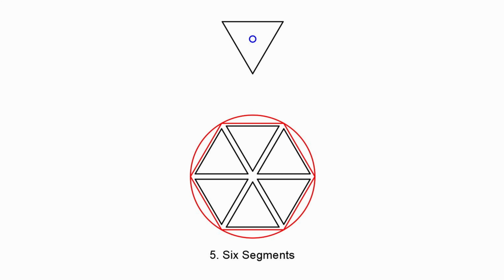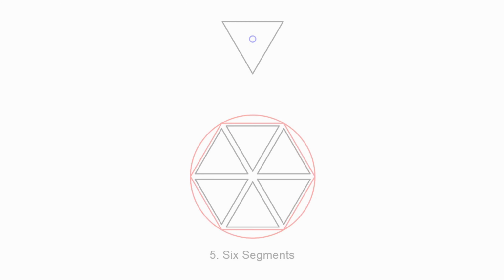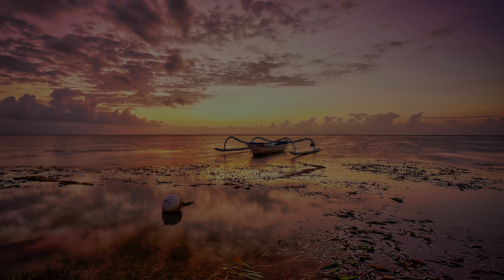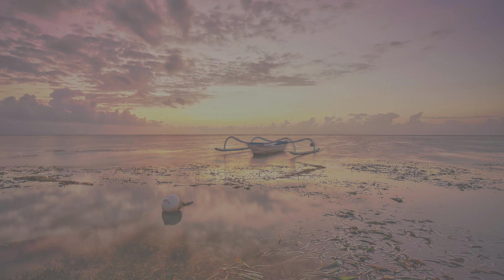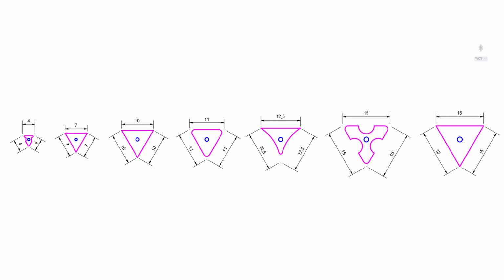And the ideal tool shape for this pattern subtype is an equilateral triangle. The shape will be an upside-down triangle, where the origin point is located at one third of the height when measured from the top. In punch mode, we need to create all the tools that we will use for the perforated pattern. The tool shapes can be a mix of non-ideal and ideal tool shapes. For this tutorial, we are going to use 7 tools. As we can see, they are a mixed set of ideal and non-ideal tool shapes.